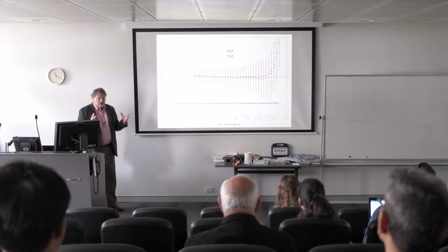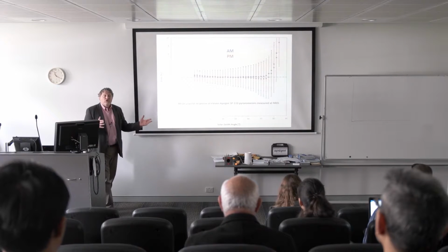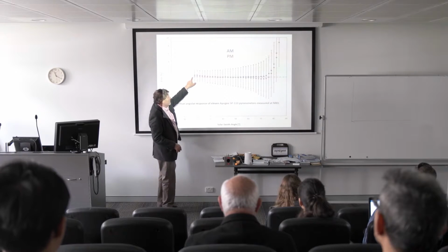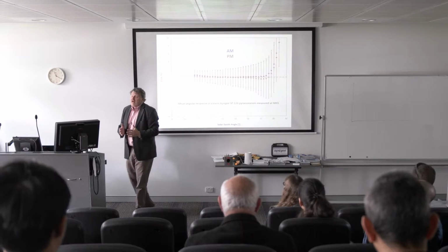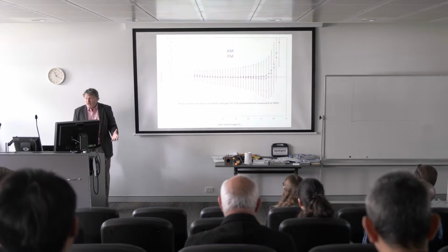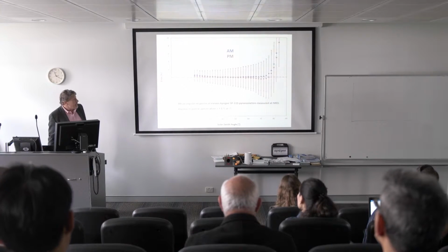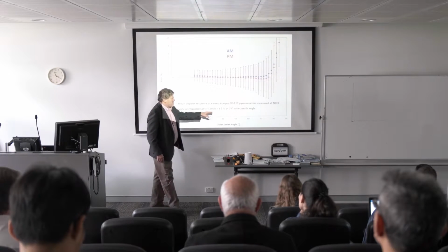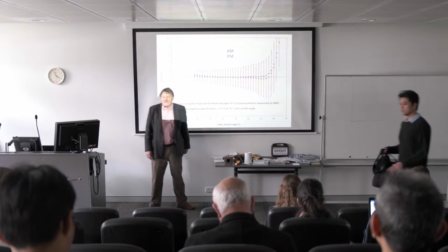But you would like these instruments to be accurate all day long, and summer and winter. How about changing sun angles? We get summer angles in here, and then we get winter angles over here. If it's not cosine corrected, it can have a big seasonal error because they're typically calibrated for summer sunlight angles. So we specify these often by the error out here at 75 degrees.